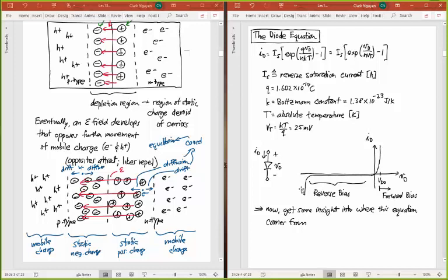It does break down at that point. We won't really talk about this point right here because in the diode we use in this class, we're not really going to worry too much. We will talk about this here, that when our voltage gets positive and positive enough, suddenly we're going to get huge amounts of current flowing through this, and basically it could support whatever current is necessary for the circuit that this is in. And so what we want to do is understand this part here especially. Why is it this part is modeled by this equation? Okay, so by the end of this you will understand this equation to some extent.